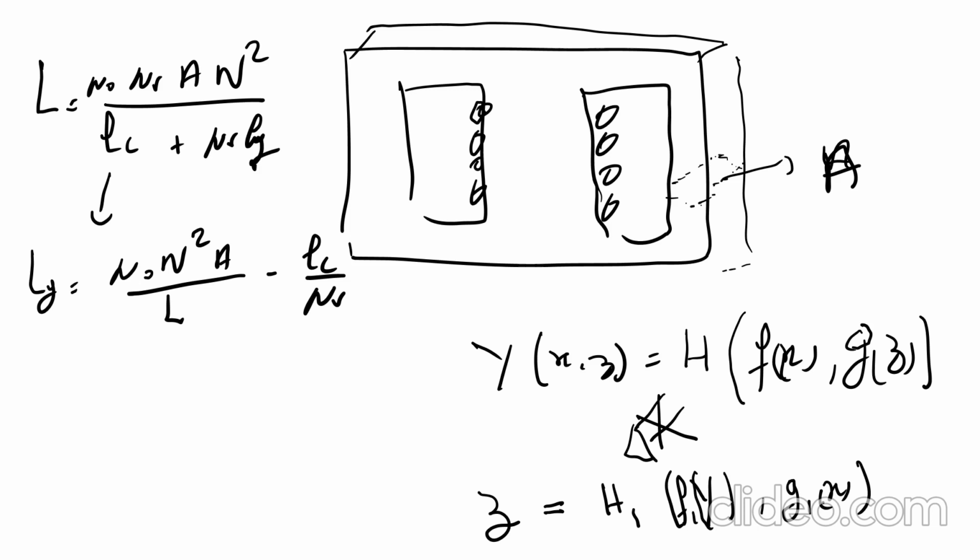What are you going to do in that case? One solution you could choose, which I don't always prefer, is to increase the cross section. But I'm using it here just to explain why the air gap does not depend on the cross section. Increasing the cross section, the magnetic flux density will reduce to its original value.